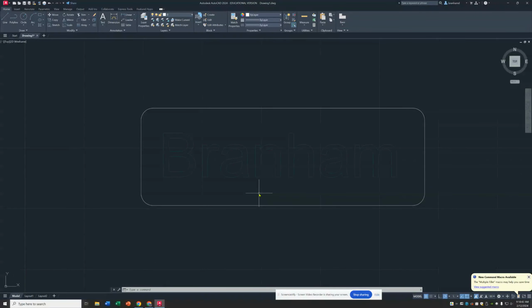The next thing I need to do is create some bridges, because if this were to plasma cut right now, it'll cut these first, and then it's going to cut around here. And so you aren't going to be able to see these middle pieces. Those would fall out. So we need to create some bridges to keep those in place.